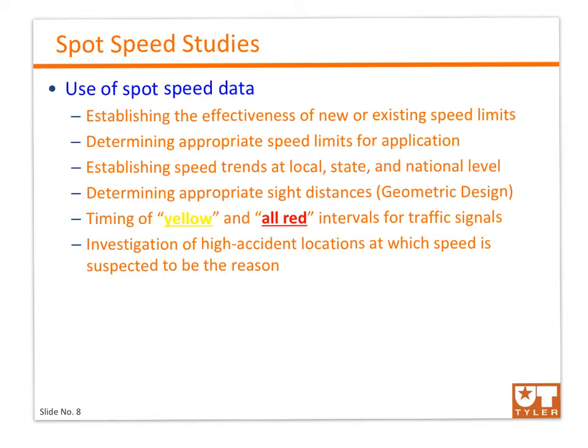If we don't know it, before we post it, we either do a study in a nearby location with similar characteristics, or we delay posting the speed limit for some time until we have collected some data to know exactly what the speed limit should be. So we would start from a default value based on the AASHTO or the MUTCD standards, until we do our own spot study for that new structure.